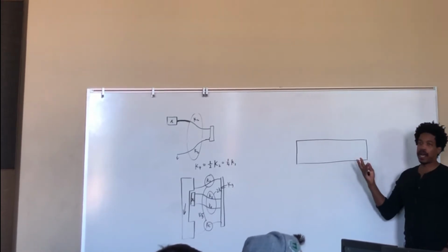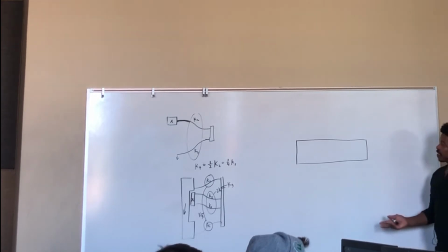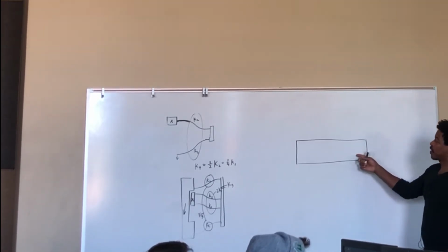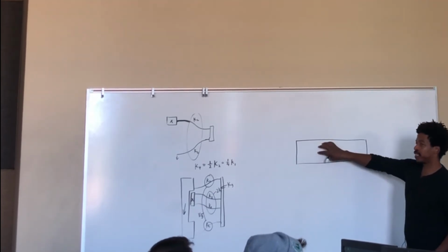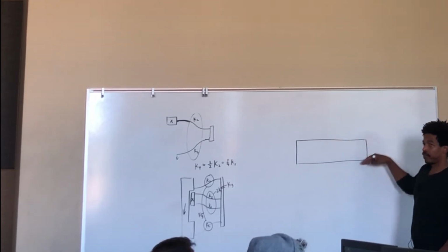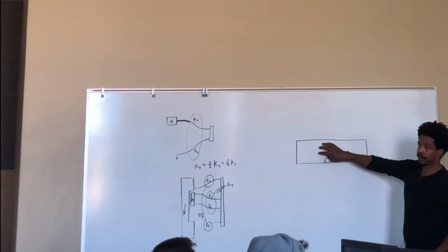And you guys have a guess. We're going to do cantilevers today, but COMSOL doesn't know yet that that's a cantilever. You have to tell COMSOL what the material is inside this and what is on the boundary. Okay, so these are the boundary constraints, and that's the subdomain.